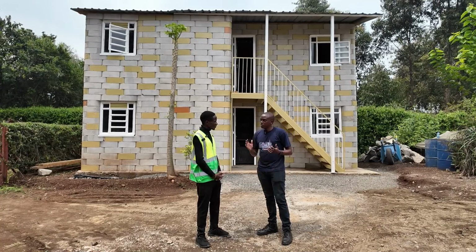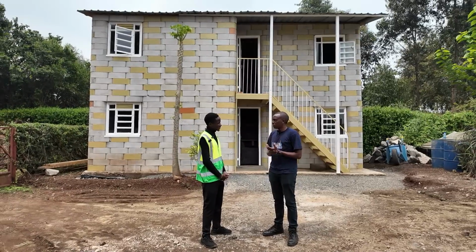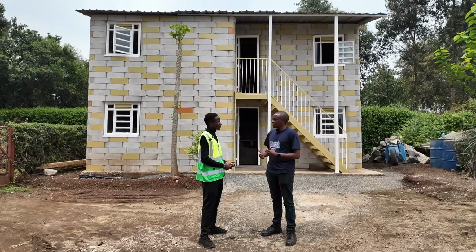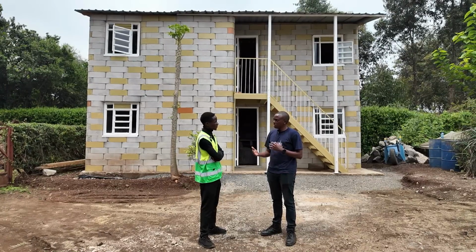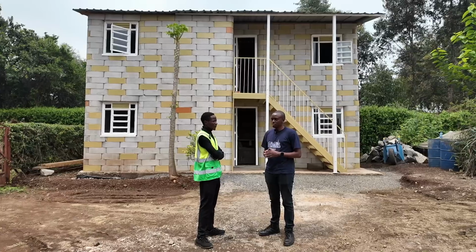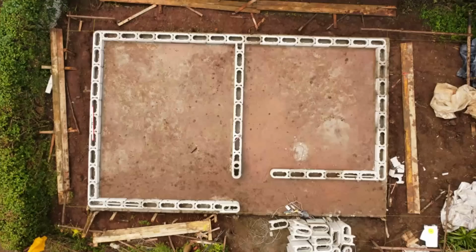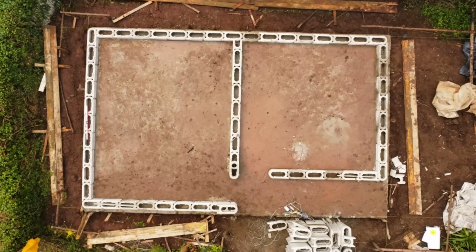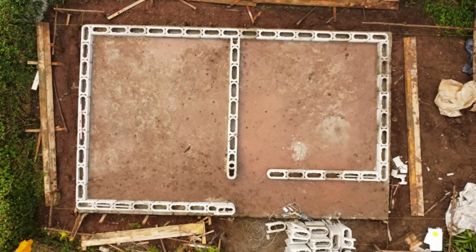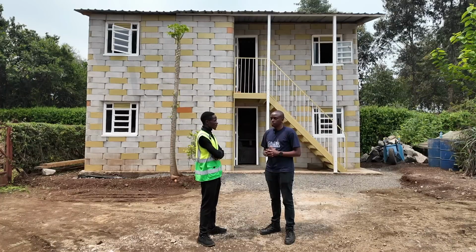Yeah, a big feature of twist blocks is the lack of mortar. You don't need mortar between the joints. Now, when it comes to the foundation, do you need any mortar to connect the blocks to the foundation? Usually, how we do it is the first course is concreted halfway. That is the first course from the foundation. It's concreted halfway, but it's done after you've done your leveling and your setting out.